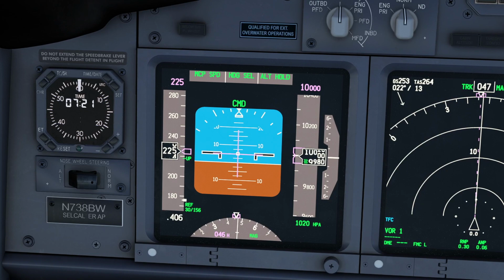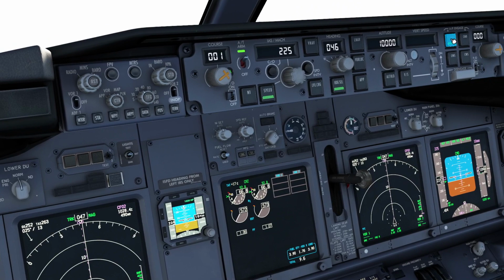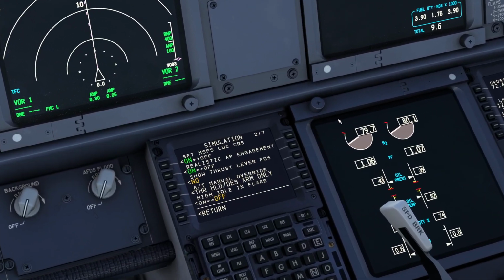A little bit of pressure pulling or left or right is not a big deal, as long as it is just a small amount on the trim and your airplane is flying pretty much what the flight director is telling you to do or what you select on the flight director. And the third one is, of course, then you press the autopilot command A, command B, or CWS A, CWS B for it to engage, okay? So it's up to you.